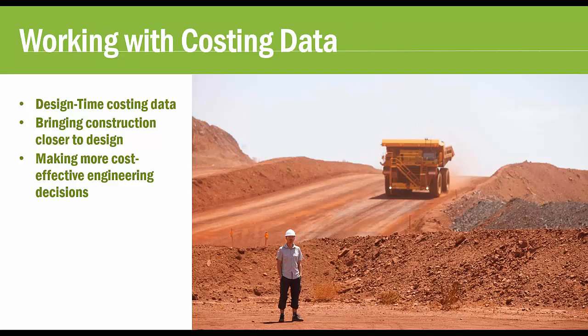because a balanced road is not always the cheapest road, and cuts and fills aren't all that matters either. Material movement, how much is moved and how far, makes a huge difference in terms of construction costs. So really it's quite a complex process that involves lots of variables.